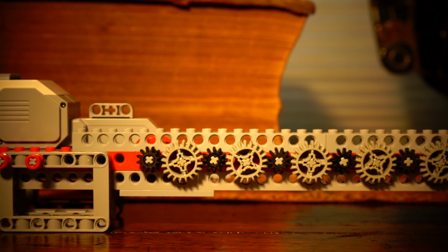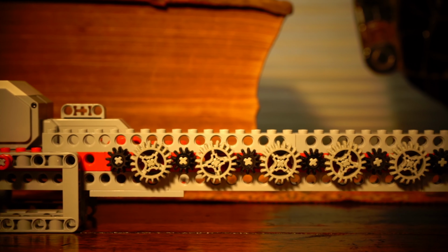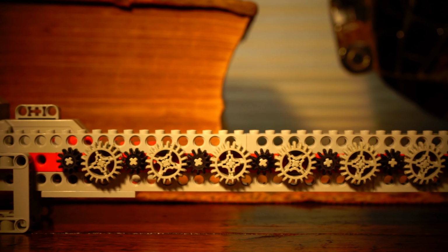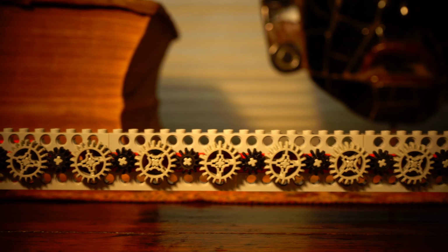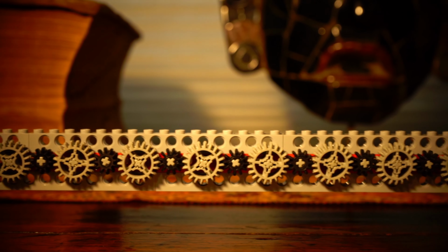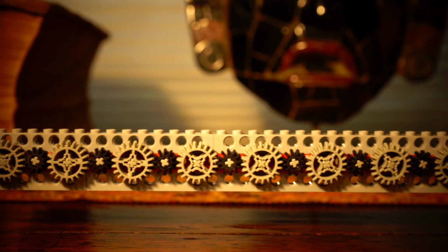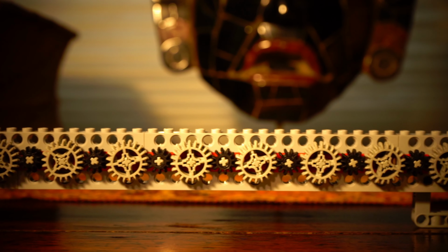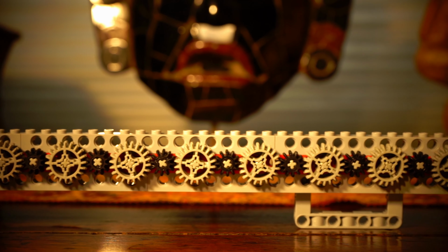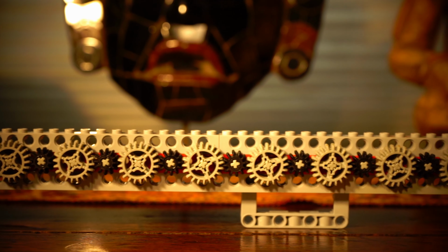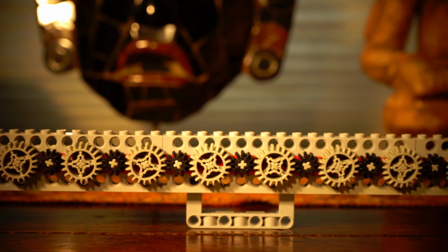Gear trains transfer motion and power from one gear to another. In some cases, this transfer of power is the only objective. You have a gear turning in one location, and you need that gear to supply power elsewhere, or possibly to apply that power in a new direction or even a new plane. Gear trains can additionally be used to increase gear speed or torque, which are inversely proportional to each other.